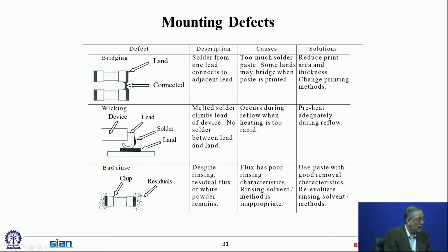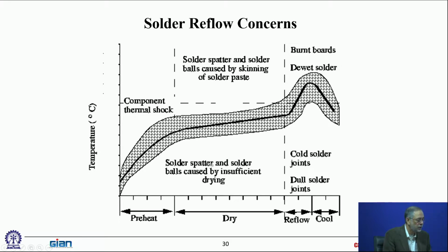Okay. Residuals: you get solder splattering. So there's talk about that over here. During the reflow process, if you heat it up too fast, then the solder splatters because all the organics are explosively volatilizing. And the solder at that stage, before it reflows, is still just a bunch of small spherical particles, micron-scale, held together with that resin binder.